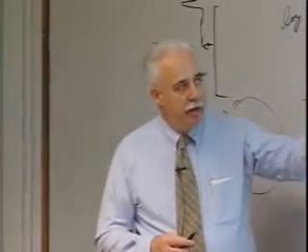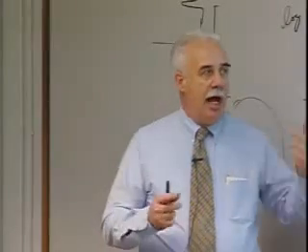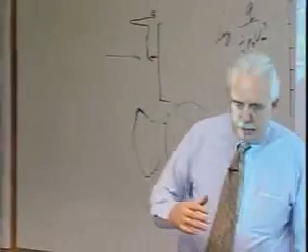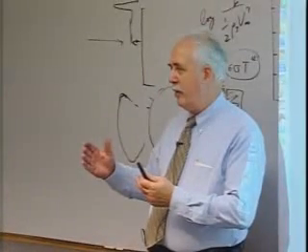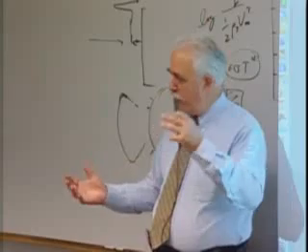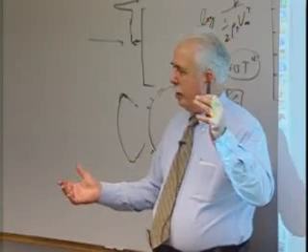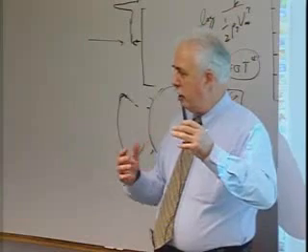On lunar return, it's a problem. However, if you look at the radiative heating, it's first order proportional to dimension, whereas the convective heating is just the opposite. It's inversely proportional, square root. So as you go up in dimension, your convective heating is less important, as we did with the shuttle, and I'll try to address that in a minute.